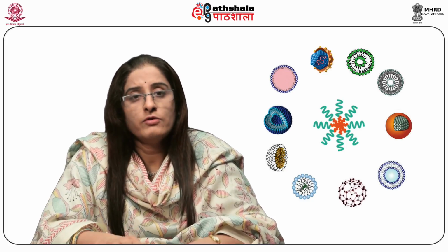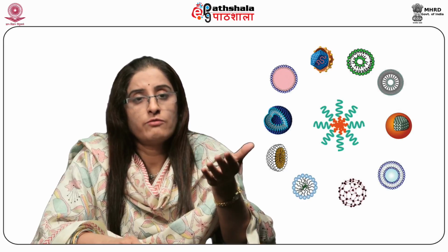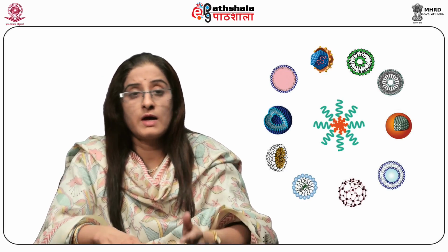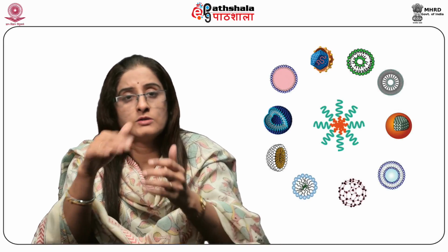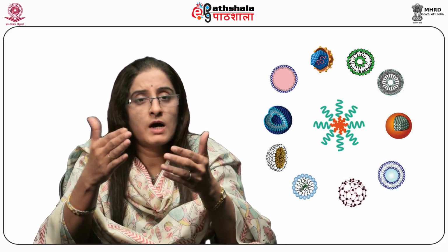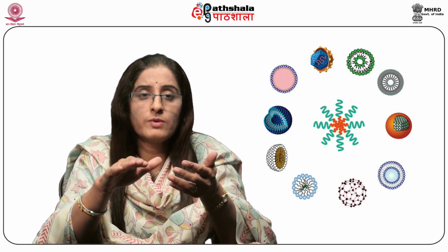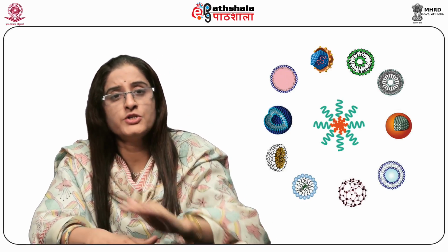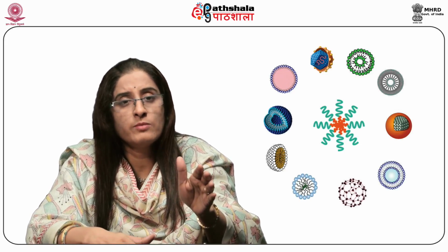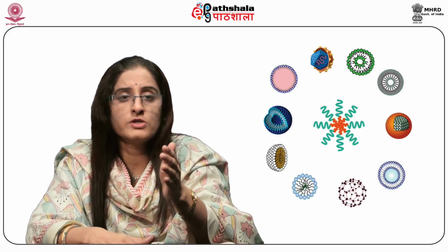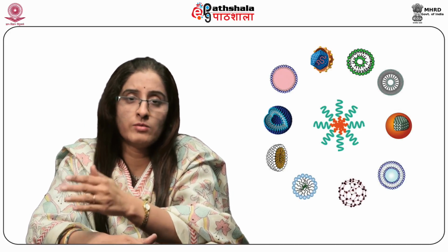As we discussed during the preparation of multiple emulsion systems, in the first step of emulsification we usually accept high shear equipment, because the primary emulsion should be very stable. If we use high shear for its preparation, it leads to a stable primary emulsion, and if the primary emulsion is stable, definitely it will provide a stable secondary emulsion.